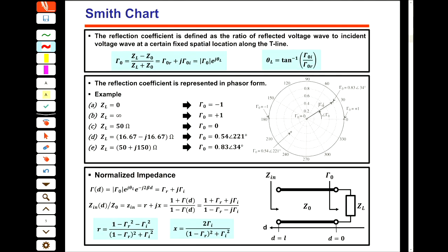All right, a Smith chart. This is what I just told you, that we can calculate the gamma of a transmission line terminated with a load ZL. At the point ZL, we can calculate the gamma from this equation. And I can understand from this equation that if ZL or Z0 is complex, then the gamma is a complex number. And then we can define this gamma with the real part of the gamma and the imaginary part of the gamma.